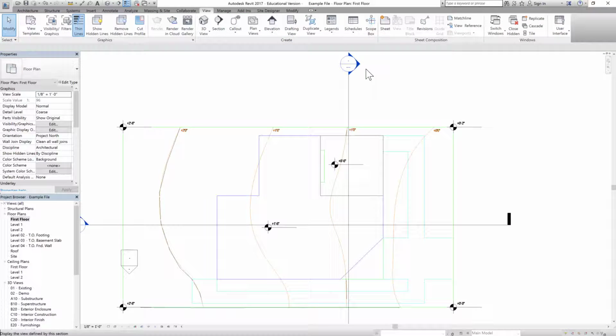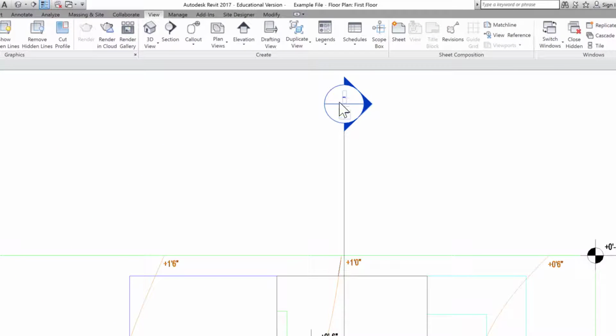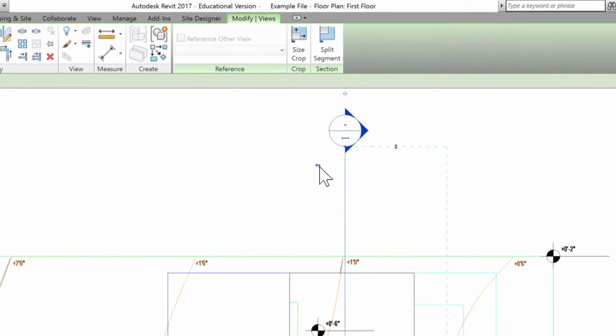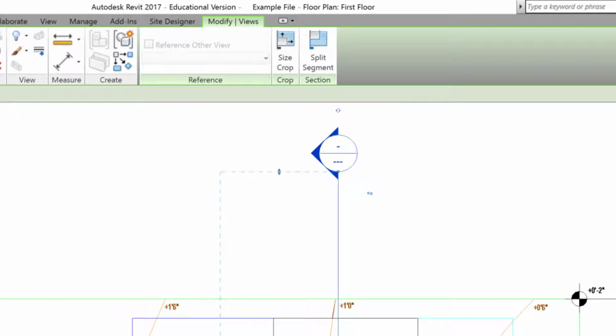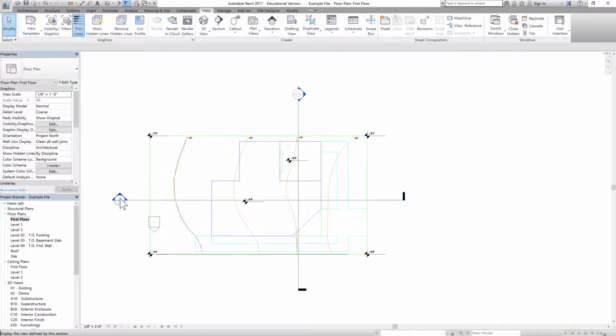Now you can change this. So you see in the section line that we have detail of this drawing where you can find this section plus in which direction we are viewing it from, and we can change it. If you click on section line, you see this little arrow, click on that and it will move. So you can change the direction of viewing on this section line. So for now we are fine. So let's go to this section.